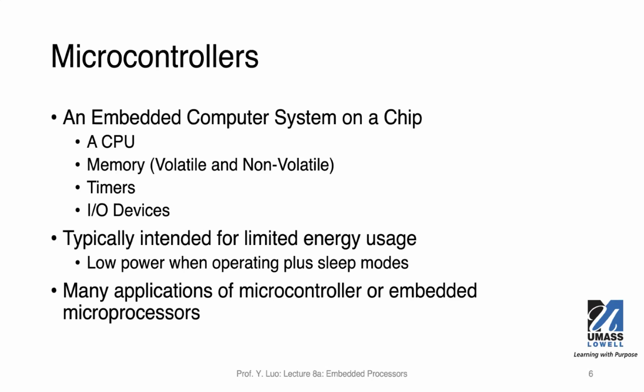I would say the microcontroller is more leaning towards the embedded domain. So it's going to be a lot more components on the chip, even much simpler. For example, the CPU core will be simpler. The data width is sometimes 8-bit or 16-bit. Some amount of memory, but with a lot of different components on the chip: timers, UART, USB, I/O ports. So when you see something like this, we call them microcontrollers.